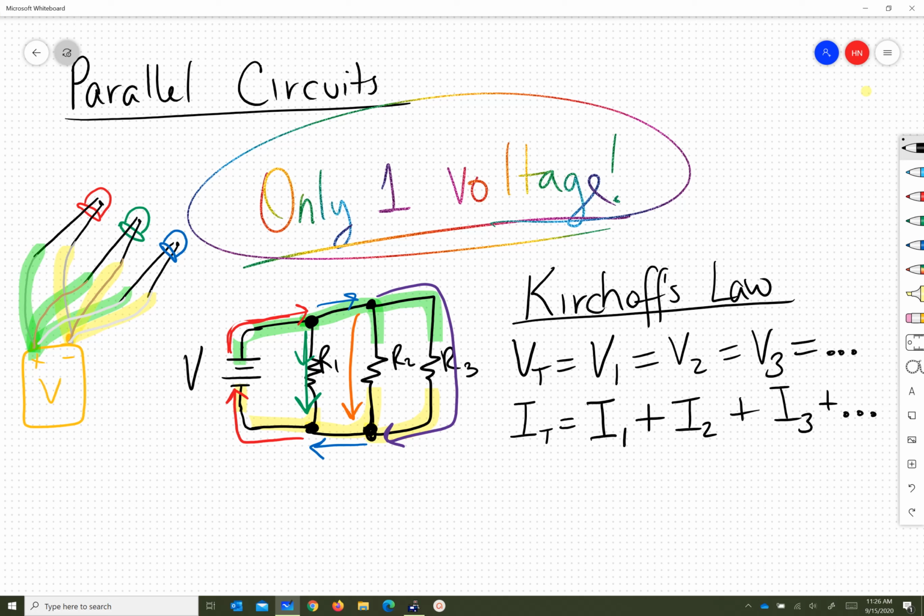Again, the blue is kind of like an intermediate current because we have a wire that splits off to two more. If we were to draw it on the circuit on the left, on the little cartoonish picture, the first LED would be the green current. Then the second one would be the orange current. And then the purple current. And they would add up. Green plus orange plus purple would equal the red current coming out of the battery. So that's what he showed, that for parallel circuits, the currents add up, but there's only one voltage.